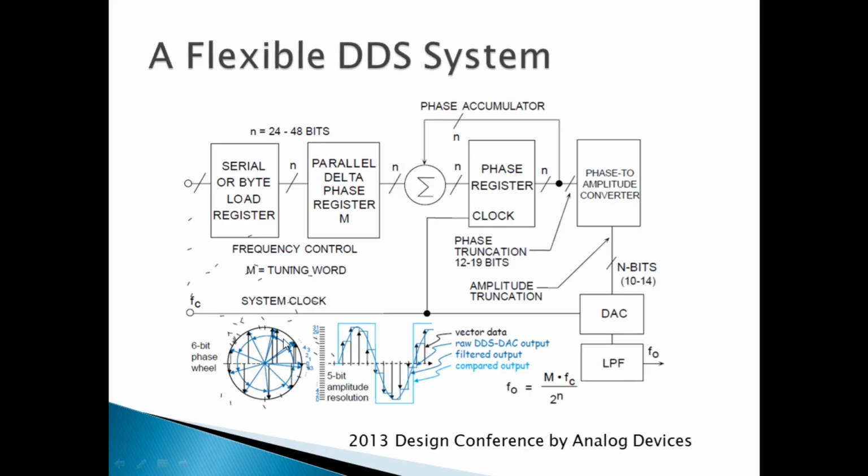That contains the lookup table where a lot of information of phase and amplitude is stored, and depending upon the tuning word, this phase register will then pick up points at various phase locations to give you this amplitude response.